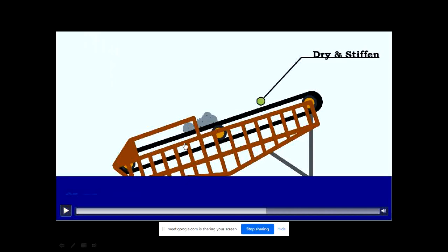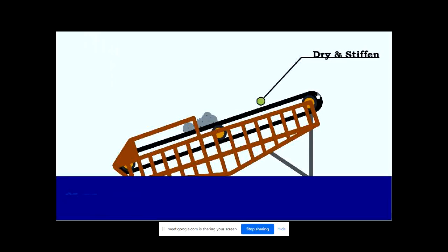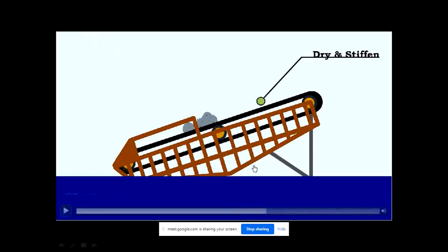So when the belt passes over the roller, there will be more vibration, so the concrete can segregate here also. And at the transfer point at the end of the belt, when the concrete is made to fall to the place where it is to be placed, it has to fall from a smaller height. If you transfer the concrete from a larger height, then the material of higher specific gravity will fall first, that is the coarse and finer grade, then the cement paste will fall.